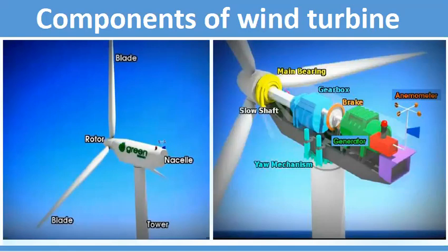A 1.5 megawatt wind turbine of a type frequently seen in our country has a tower 80 meters high, that means 260 feet high. The rotor assembly, blades and hub, weighs 22,000 kilograms. The nacelle, which contains the generator, weighs 52,000 kilograms, and the concrete base for the tower is constructed using 26,000 kilograms of reinforcing steel, contains 190 cubic meters of concrete, and the base is 15 meters in diameter and 2.5 meters thick near the center.